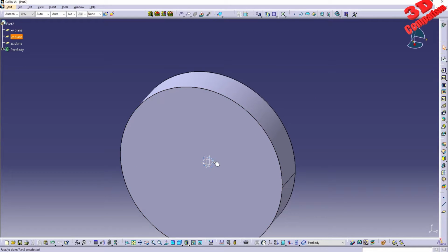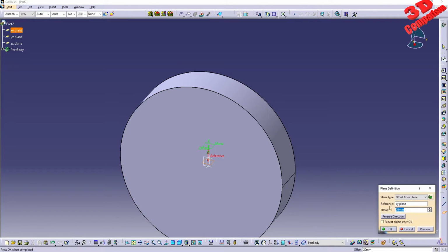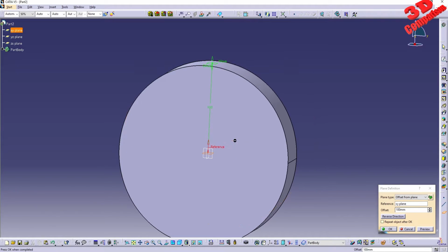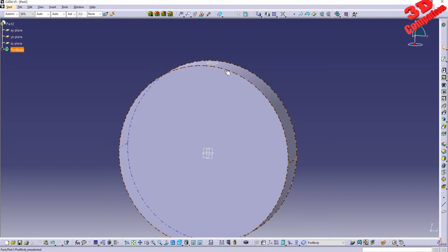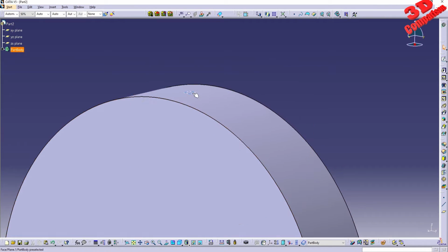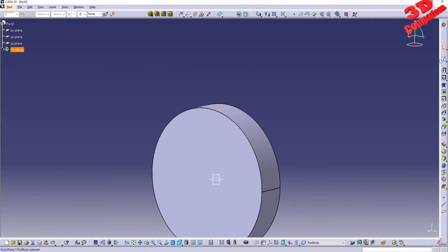Now, since this was created directly within the Y and Z plane, if I want to do a cut which will be perpendicular on the Z-axis, I can easily do that by going over here. I can elevate, I can offset a plane. In this case, I know that a plane at 100 will be, let's say, tangent over here. As we can see, we have that plane.